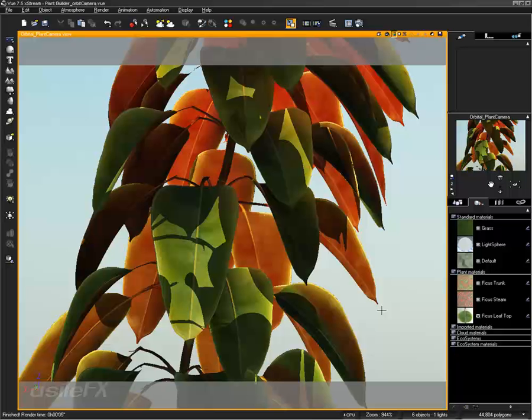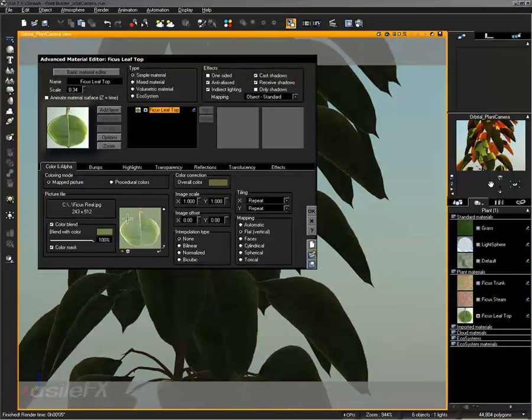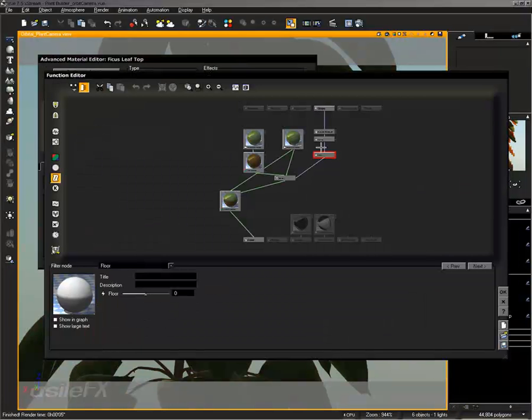And the transition amount, in this case, with this harsh of a contrast and with the leaves really drooping like this, like I said, that doesn't happen a whole lot of the time, but what we might need to do is adjust that threshold and the transition amount. You can also change the threshold if you want to bring it down a little bit more.